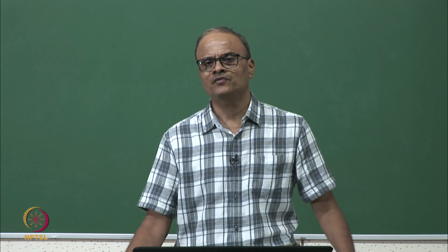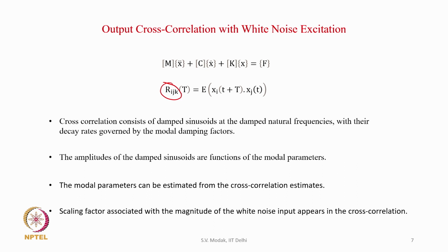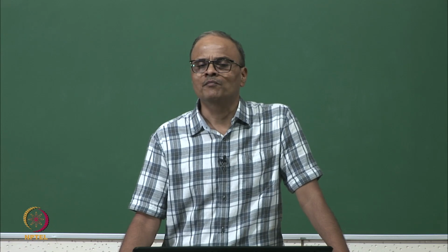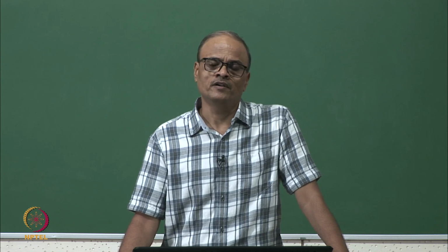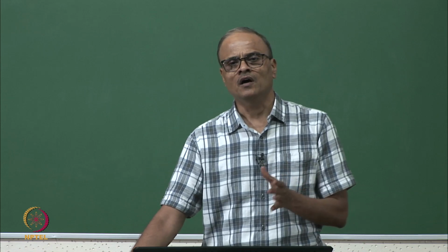So, one consequence of the lack of information about this scaling factor is that the mode shapes obtained by operational analysis are unscaled, right? They are not mass normalized as we obtain in case of experimental analysis. So, the mode shapes are associated with an arbitrary scaling factor.